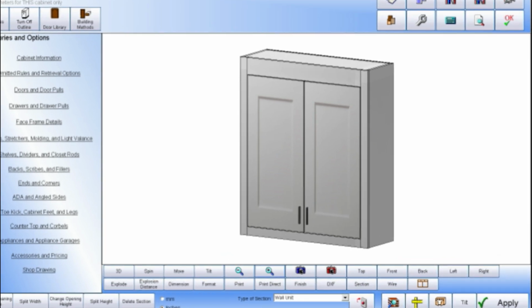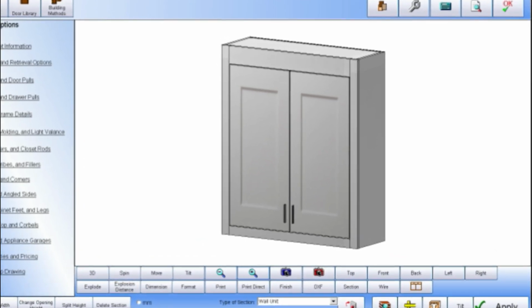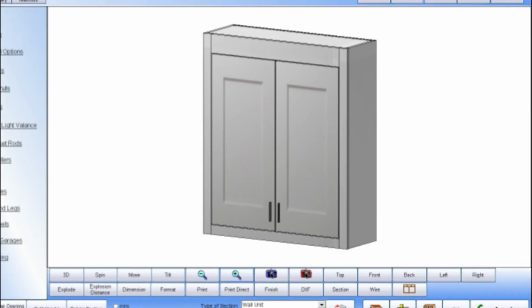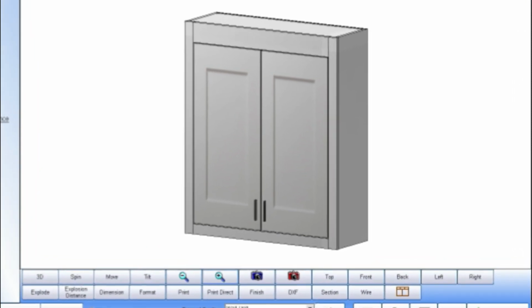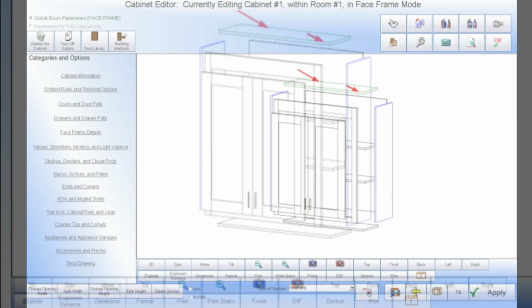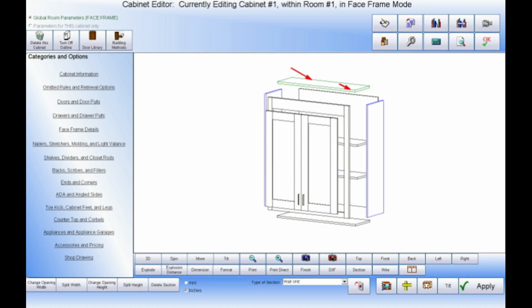The negative 100 rule is one of the most useful as well as unique concepts in Cabinet Pro that allows our cutlist and CNC processing to be essentially material independent. For better viewing during the following explanation, I have colored the outline of our cabinet top green and the outline of our cabinet's unfinished end blue.